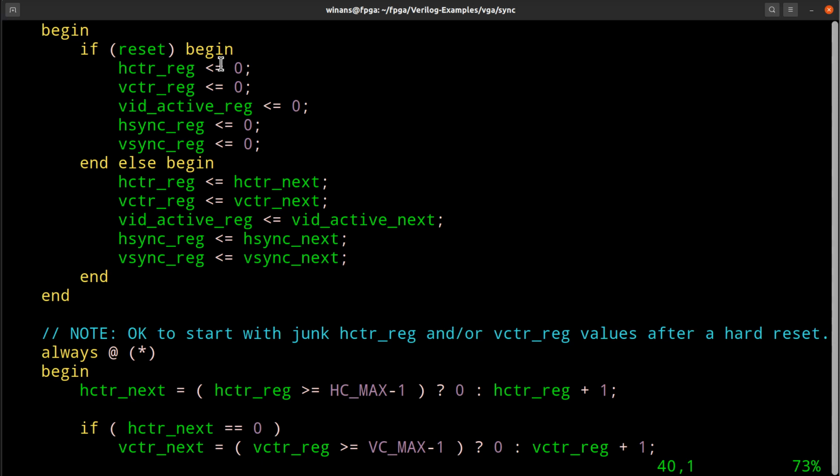I'm going to start in row 0, column 0 of the active video region in a free run until I get to a horizontal sync, and I'm going to probably waste an entire frame of video, if you think about it. If I was to write the code that runs in the video monitor, for example, which is what I'm getting at here, what does it do? I would wait until I got a vertical sync pulse before I did anything.